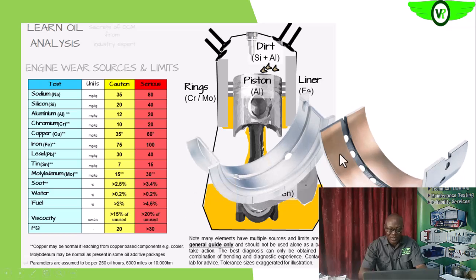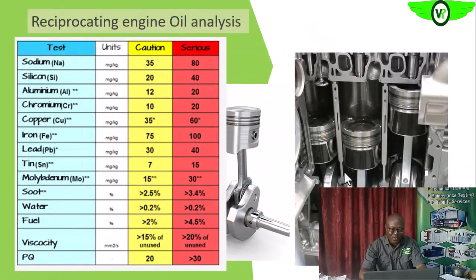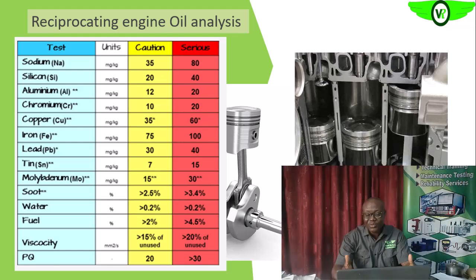So these are the metal bearings. You see the parts with which it is made. In a reciprocating engine, condition monitoring techniques like vibration and infrared thermography will not be too effective, because we have so many forcing functions. We can use the overall vibration level, but the movement of the piston will contribute to the vibration.